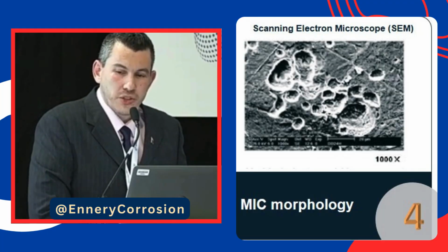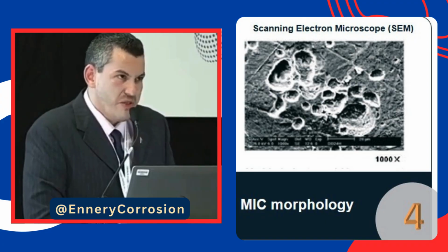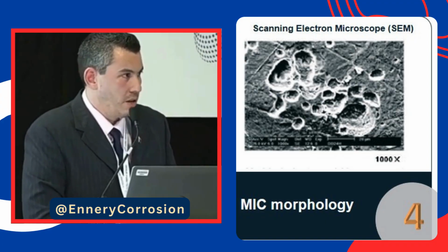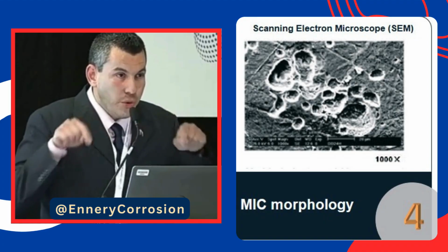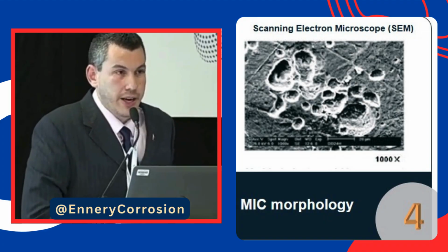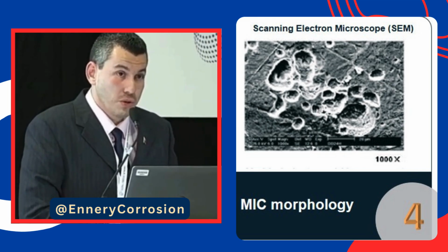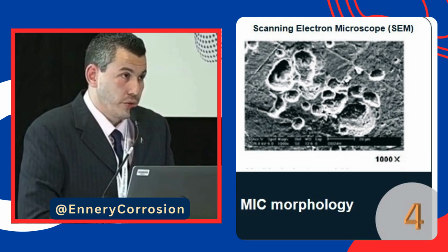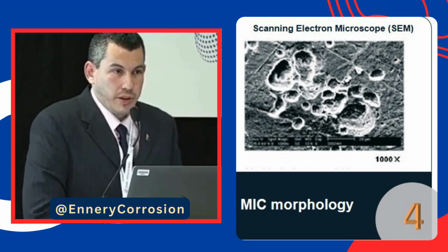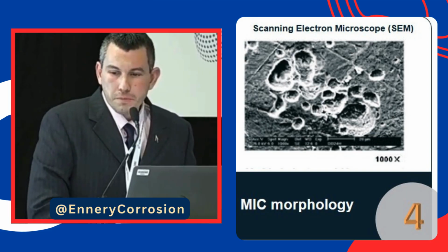Because as you can imagine, it's not the same story to have localized corrosion, where you will have maybe 5 millimeters per year of material loss just in, let's say, 1 square centimeter. You will have a leak in a couple of years maybe. And then if you're using corrosion coupons just to calculate uniform corrosion, you are lost. You are doing it wrong. You might have a misleading impression that you have a low corrosion rate.